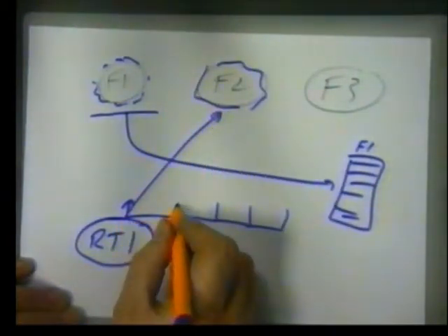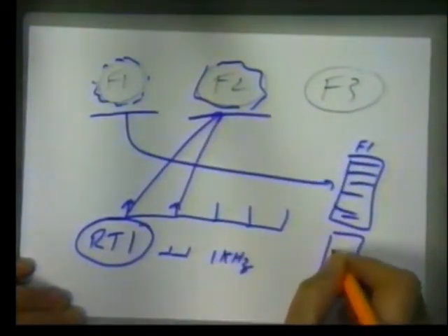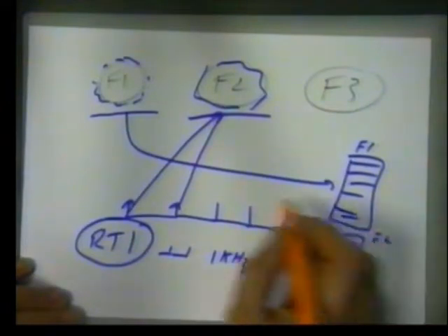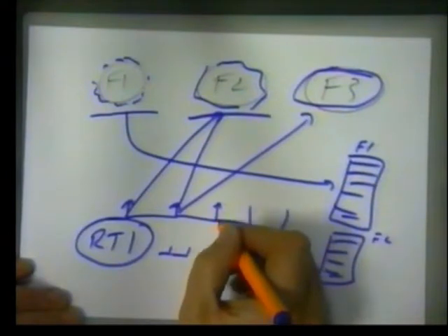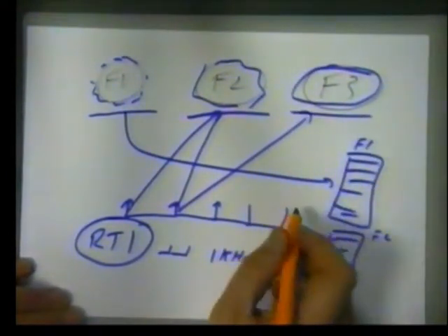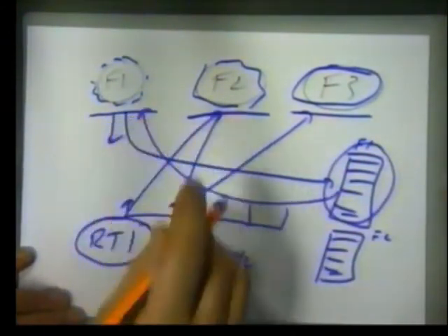So that now runs until that interrupt occurs. When this interrupt occurs, this task is suspended, the stack frame is created for function 2, and then function 3 is started. On the next interrupt, function 3 will be suspended, and the contents of the function 1 stack frame is restored, and we restart it. So what we're doing is we're time slicing. We have these functions. They're not designed to be chopped up. They are whole functions. They're either started and left to run forever, or they will have a natural completion, but they share the processor resources.